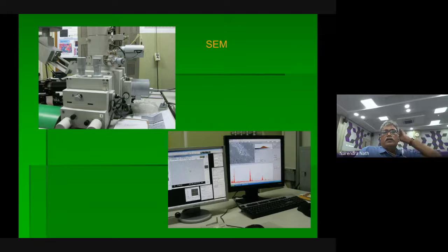You should cut at low speed. If it is high speed, because of the temperature, transformation will take place in the material right there. So very low speed, and you have to monitor very carefully and take 20 mg specimens. Collect a few, say 5, 10, then weigh which is closer to 20 and which is flat. That one you can choose for DSC studies. That gives a nice result. And this is scanning electron microscopy.